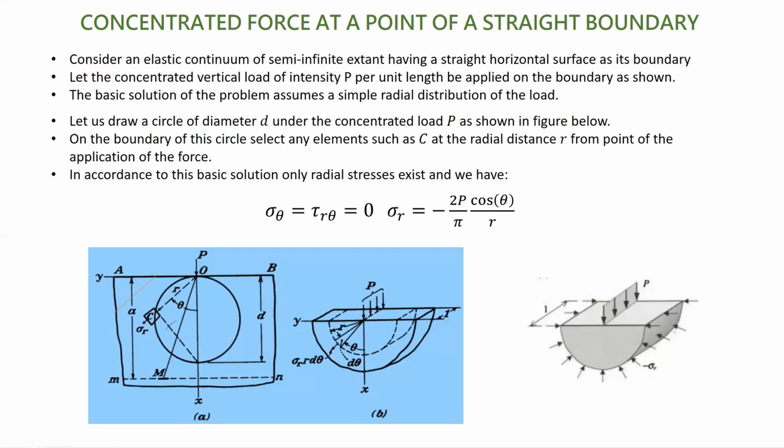Now, one of the common problems we did not address that well in mechanics of materials is what happens if I have a beam and a concentrated load P is applied on that beam, a sharp concentrated load. We generally say that in the vicinity where the load is applied, we have a large disturbance of the stress field.